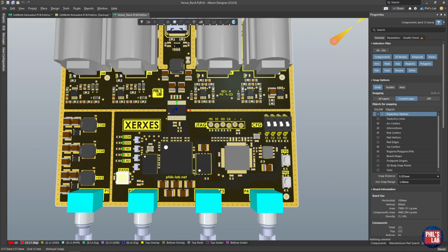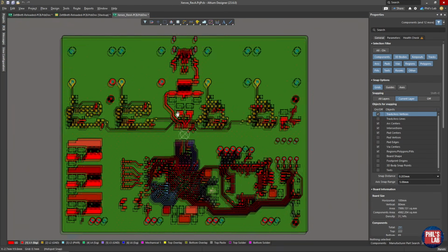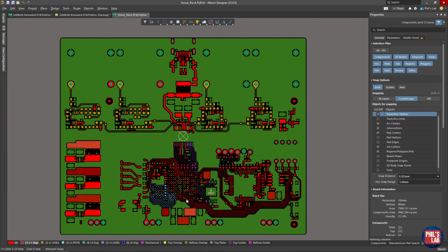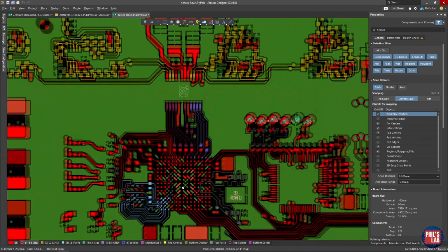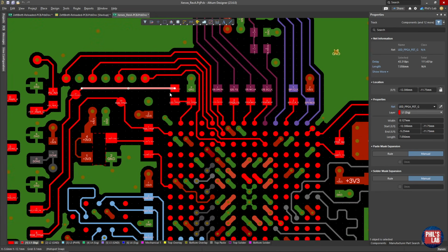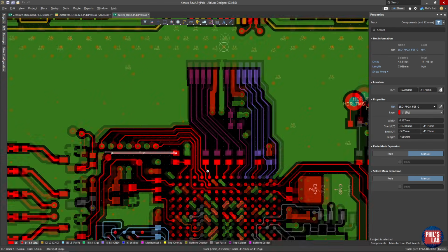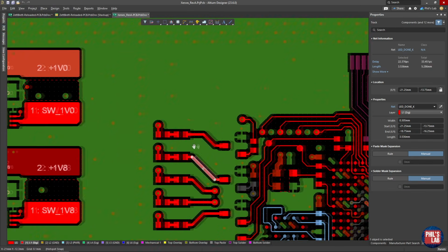To illustrate that many different sizes of PCB traces and planes are indeed used, we'll be looking at, for example, this FPGA-based audio DSP development board I designed. This contains numerous ICs, both analog and digital, high speed, power, and so on. And you can see we have various different traces and trace sizes. We have rather thin traces, which might be these signal traces. They're routed in a certain way, maintaining space. But we also have these thicker traces that might be for power.